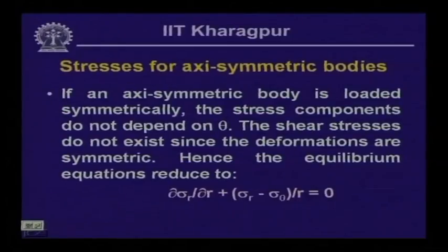And if the loading on such a body is symmetrical, you have a perfectly symmetrical body with loading perfectly symmetrical in its vertical direction, then if we take any cross section or any longitudinal section for that matter, say a section through the diameter, at every section the level of stress will be the same.